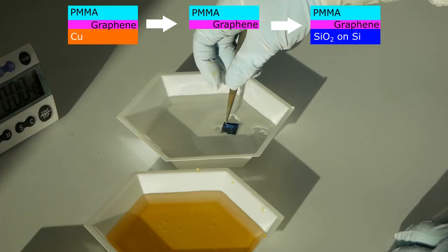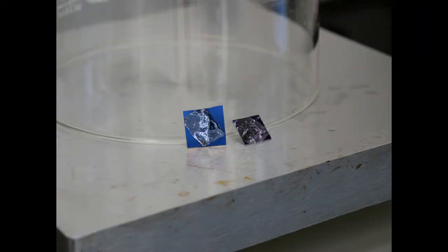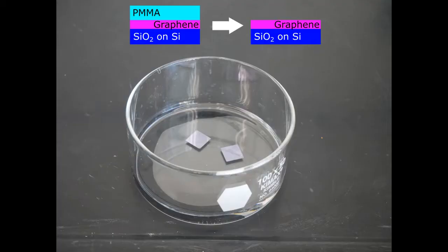Then we use a silicon substrate to remove the PMMA from the final bath. The sample is then placed at an angle on a hot plate to dry, then bakes close to the glass transition point for PMMA to ensure good contact between the graphene and the substrate. Finally, the sample is placed in NMP overnight to remove the PMMA transfer layer.